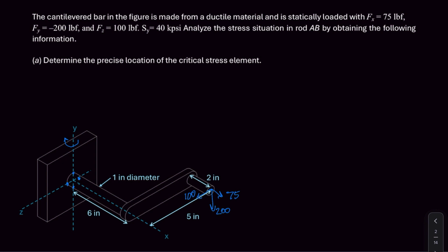So we can guess here that the critical location, if we were looking at a cross section of it here in the YZ plane, we would see that the critical locations are these two points for the two bending moments. And so the resultant would be a critical axis for that bending moment somewhere over here, which would mean that the critical location for the stress is going to be 90 degrees from that.